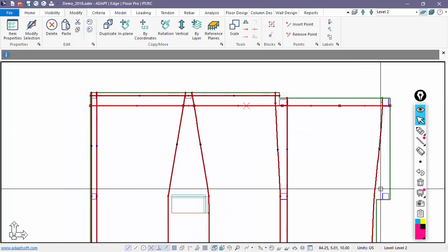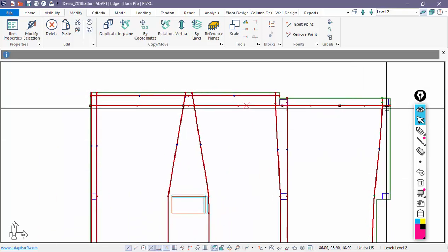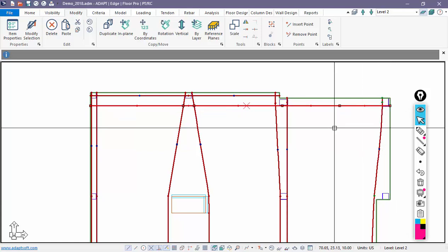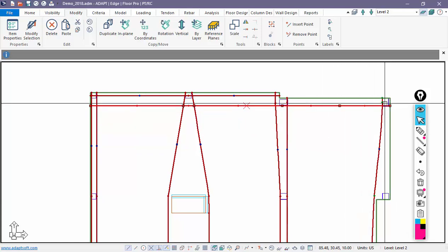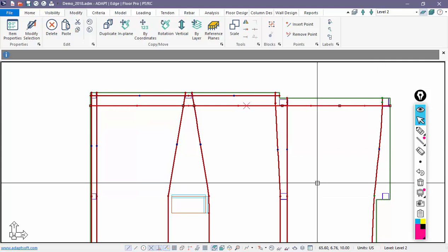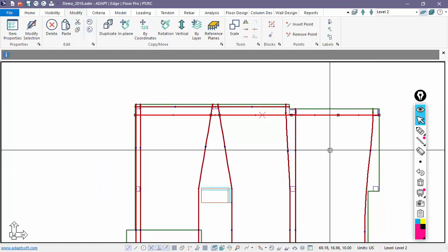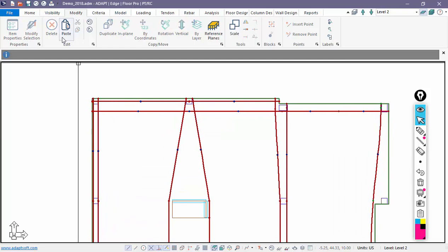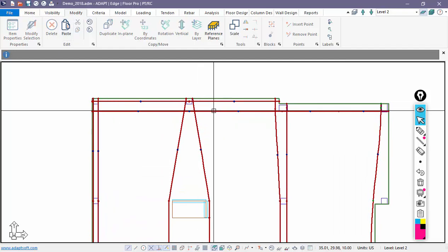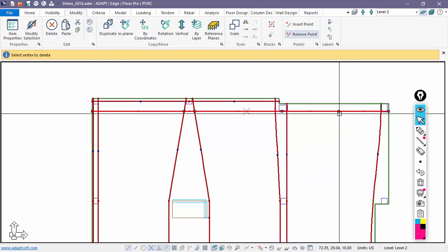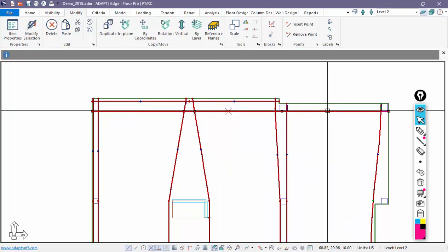And then we anchor it out here at the perimeter. Again, you could make a case this is a cantilever, so we need another point, but we'll just assume that we're running it to the edge of the slab. So we have an extra point actually. So let's save the model, select this, and we'll right-click, delete this vertex here, and we're left with this tendon.